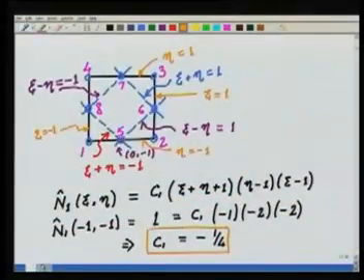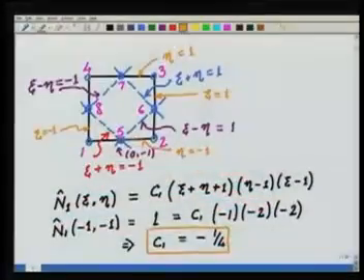Similarly, if I have to form N2, the shape function N2 will be what? It has to have a value 1 at this point, and it should vanish on all other points. So by the same token, if it vanishes on this line running through the nodes 5 and 6, on the top line running through the nodes 3 and 4, and on the vertical line running from nodes 4 to 1, then it vanishes everywhere excepting node 2.